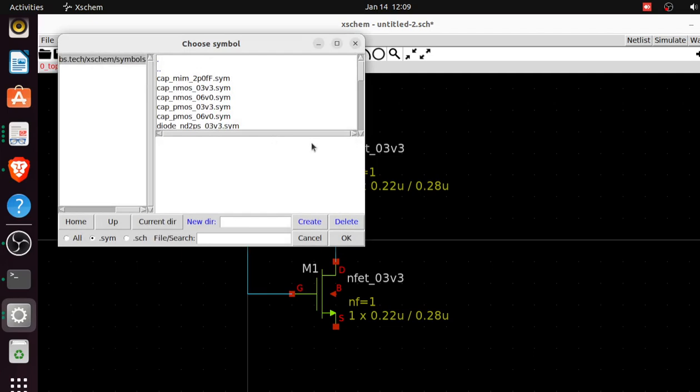For now, things like voltage source, your netlist label, like your pin label, and all those things, and current source. What else? The ground. You don't have them available, or you don't need to pick those ones from the PDK library. So that's where the scheme library comes in. All those generic devices, you pick them from scheme.